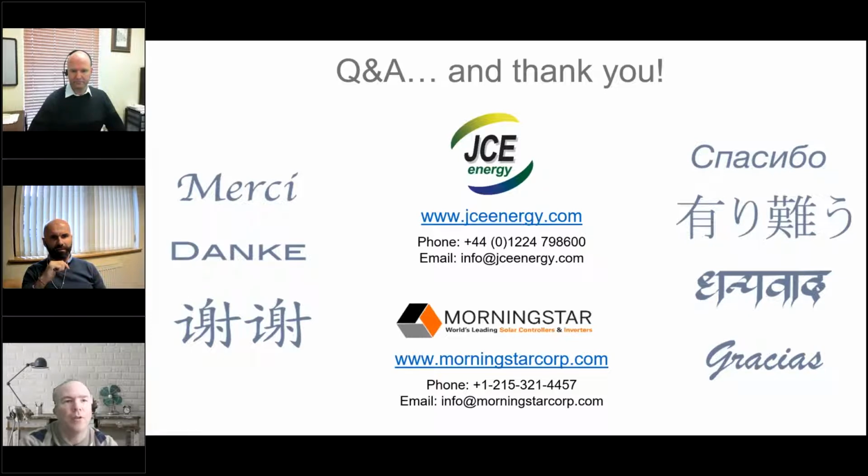Okay, and is there anything that you would like to add to that, Marco, for your systems? Anything that you've experienced? Yes, for example, in the North Sea, we experience every time temperatures well below zero, so -10 and -20. So for the charge controllers, as Brad said, there are not any problems, of course, because they are rated to -40. Of course, the lowest temperatures become a challenge, especially for the batteries. But when we design the system, we incorporate the temperature compensation factors for the batteries. So we add an extra capacity to the battery to overcompensate the effect of the lowest temperatures.